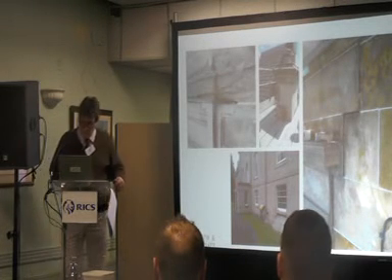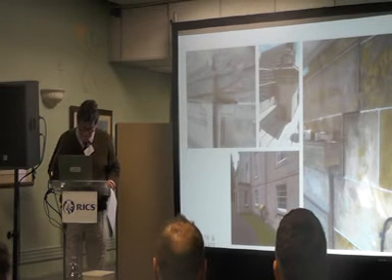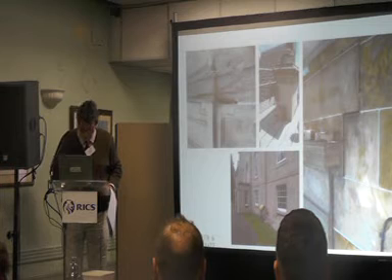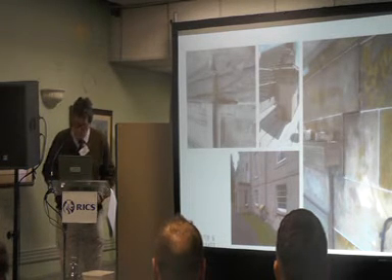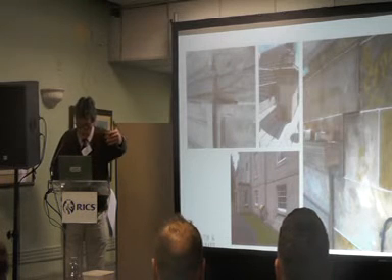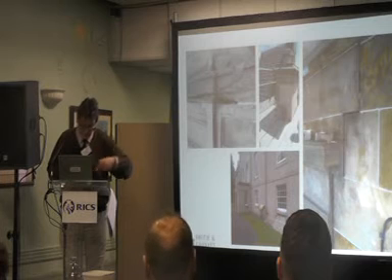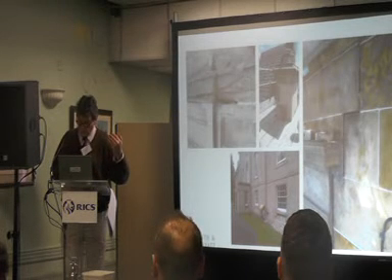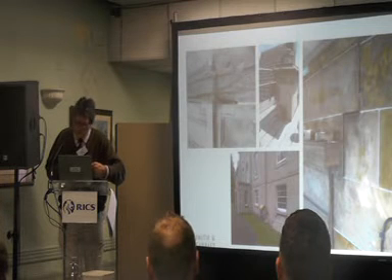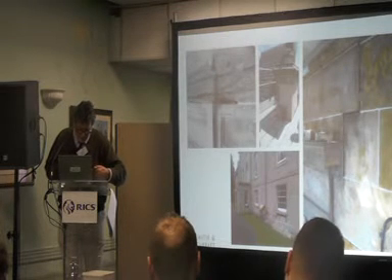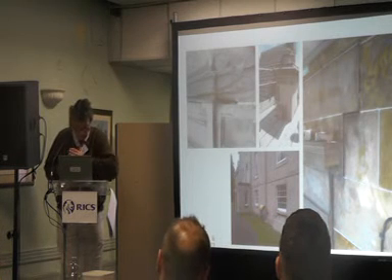On the right, we've got beautiful lime pointing. That's lime putty pointing. Really fantastic, but it misses the point. What we have there is the front of a shop falling forwards towards the high street because, again, the shop's been opened up over the years. People have knocked down walls and whatever. Now it's got no, well, it has now, but at the time I took the picture, it had no restraint holding that facade back onto the building. It wasn't in any immediate danger of dropping out, but it is now restrained back through the walls that hold the whole terrace together.